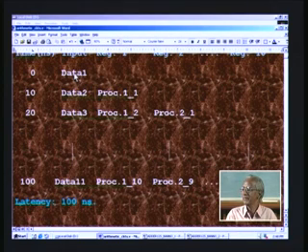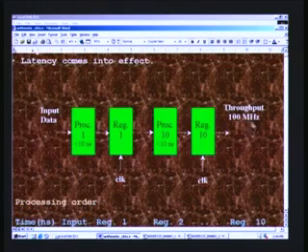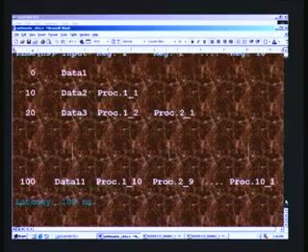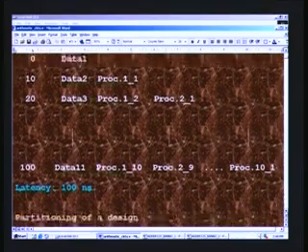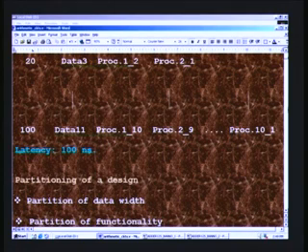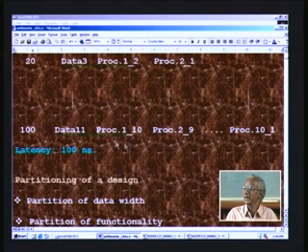So, that means to say we started the computation here only at 100 nanoseconds, and this process has output here. This is nothing other than the final output as we have seen here. And naturally you start getting the first output only after 100 nanoseconds, and that happens to be the latency here, and that is how the data flows via the digital pipeline, so to say.